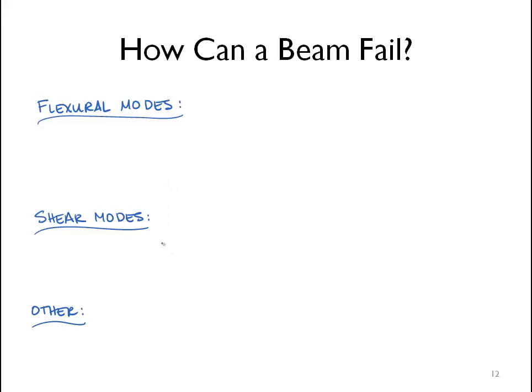That's going to be the type of mode that concrete beams are most sensitive to. For us, steel beams are going to be much more sensitive to flexural failure modes on a more global level than on a material level. And so we will see less emphasis placed on shear failures when we're talking about steel and more emphasis on some other global flexural modes.